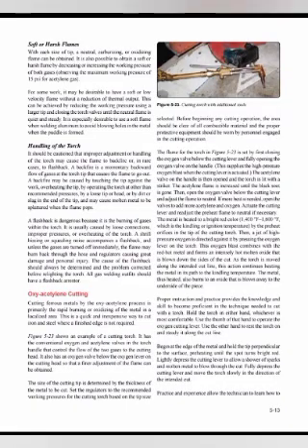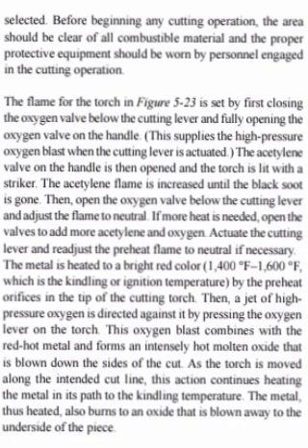Before beginning any cutting operation, the area should be clear of all combustible material and the proper protective equipment should be worn by personnel engaged in the cutting operation. The flame for the torch in figure 523 is set by first closing the oxygen valve below the cutting lever and fully opening the oxygen valve on the handle. This supplies the high pressure oxygen blast when the cutting lever is actuated.